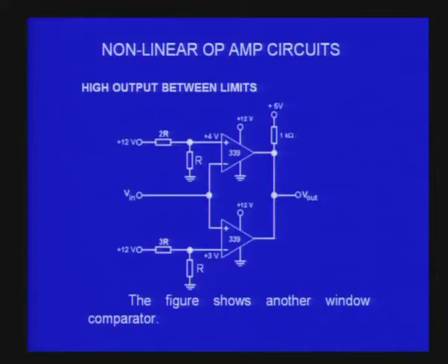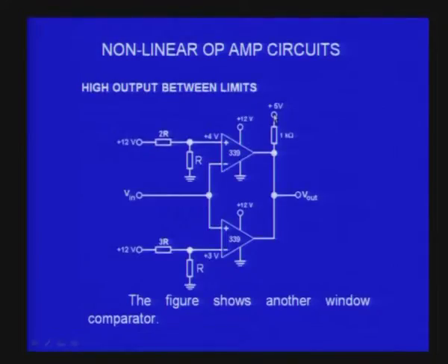TTL logic is one of the good families of logic circuits, where the operating voltage is 0 and 5 volts only, and therefore, if I use a pull up resistor and connect the output of the 2 op amps to 5 volts, then the output can never be beyond 5 volts, it will be 0 to 5 volts only. The actual op amp power supply in this case is a single supply with a plus 12 volts and a ground, as you can see in the circuit. Only the output I use a pull up resistor and connect to 5 volts, so that the output will only go from 0 to 5 volts and not minus 12 volts to plus 12 volts, as in the case of the 741 op amp.